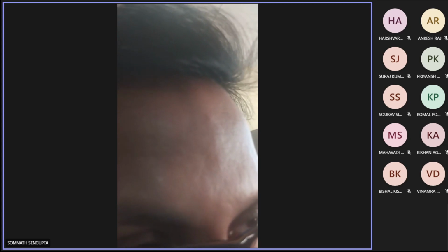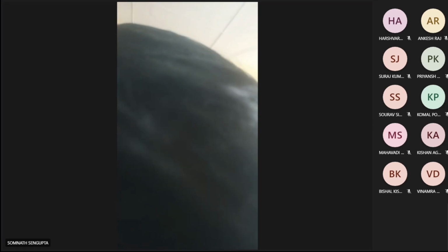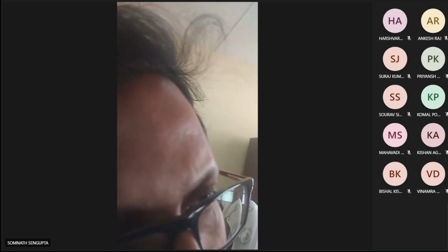So there is a transition at the middle of the bit. That is the concept of Manchester coding. So the DC component is removed. This is one advantage.